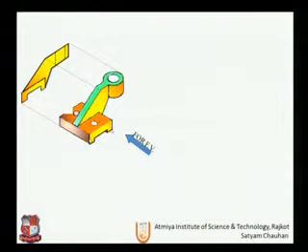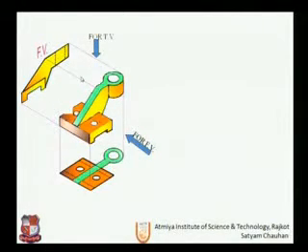So this yellow line and this circular portion will become a rectangle for the front view, and whatever diameter inside is drilled is represented by the hidden line. For the top view, this complete diameter will be visible and all the green surfaces will be visible.